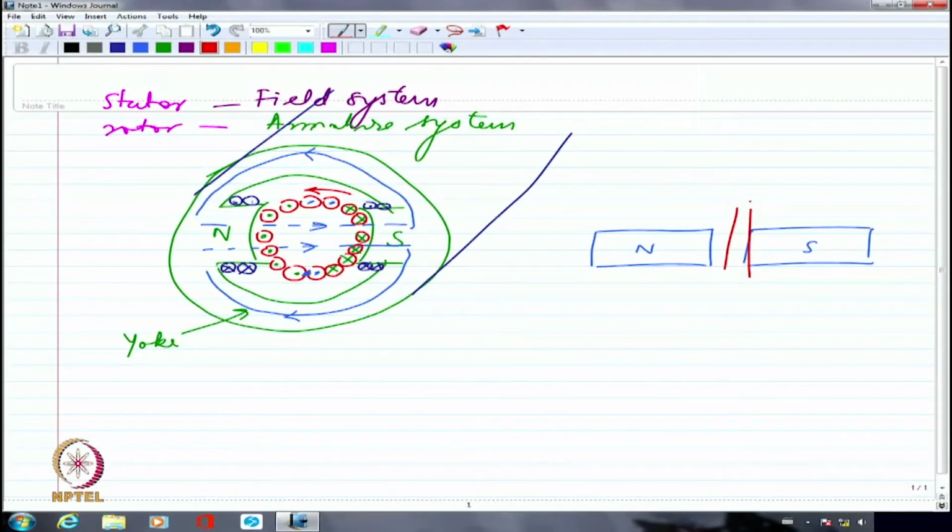How can it be? That question was arising for some of the students. Please understand that in the cusp, they are hardly going to have much of current because the current is completely changing its direction from dot to cross and cross to dot. So, even if they are of opposite polarity, it should not matter so much because they are anyway on the verge of changing.